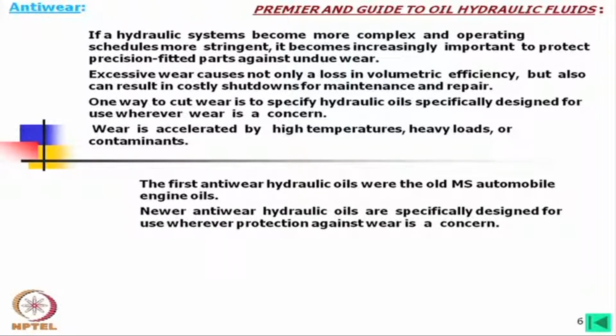Newer anti-wear hydraulic oils are specifically designed for use wherever protection against wear is a concern. This means depending on the type of wear and type of application, there are different additives added to the hydraulic oil, and we say for this material the anti-wear hydraulic oil will be this one. This specification is available with the manufacturers of oil.